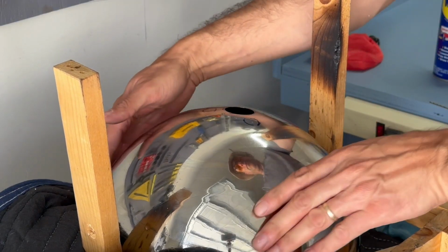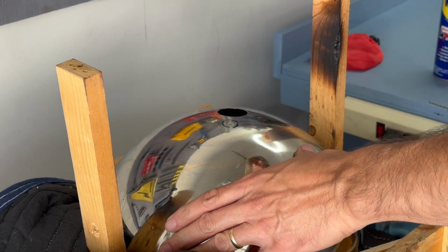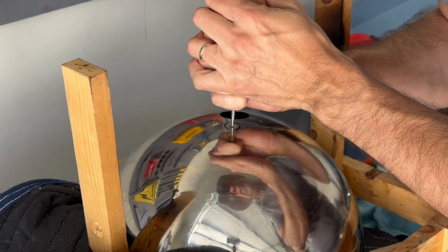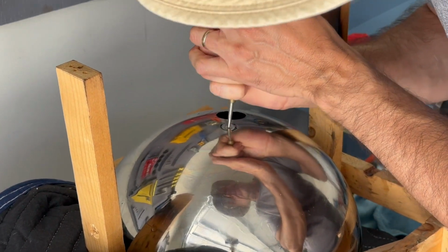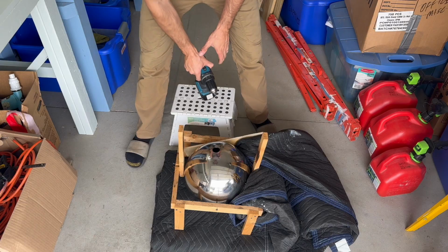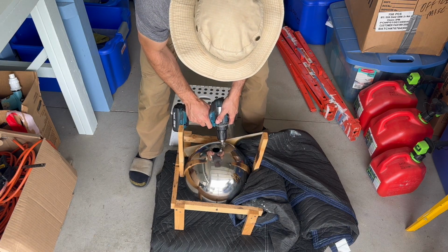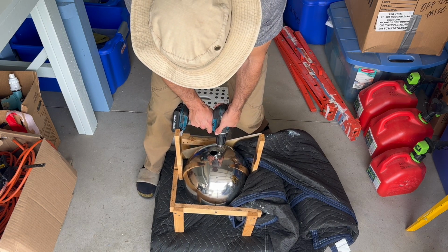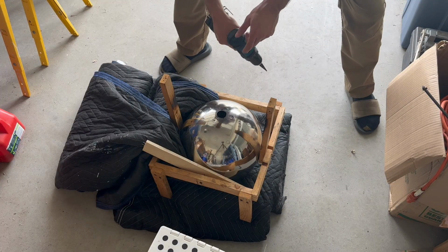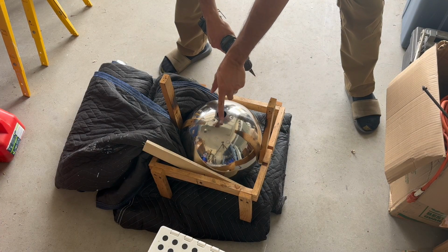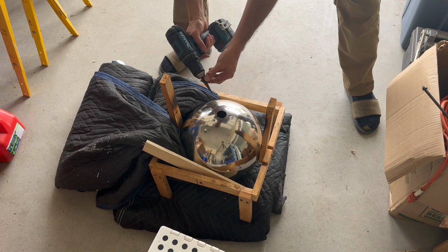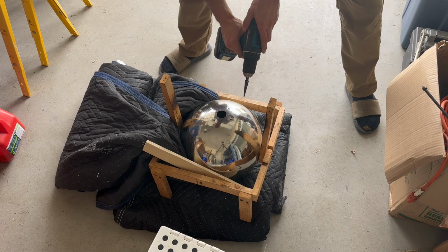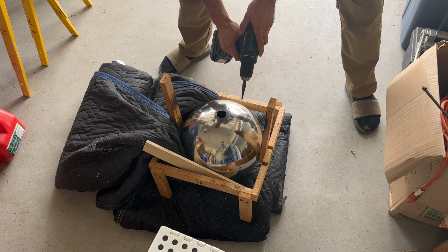All right, so now we'll do the three remaining holes. Make that punch hole a little bit more pronounced. I'm finding that on the floor here I have more leverage. So now I have 3 little holes drilled around the big one, and I'm ready to use the step drill. And I'll just very carefully try and get to the right diameter.